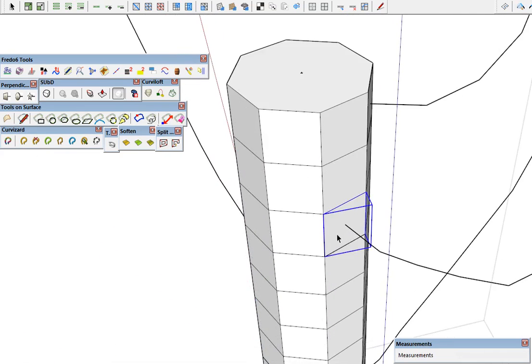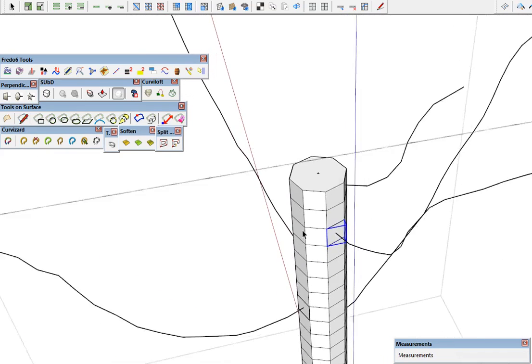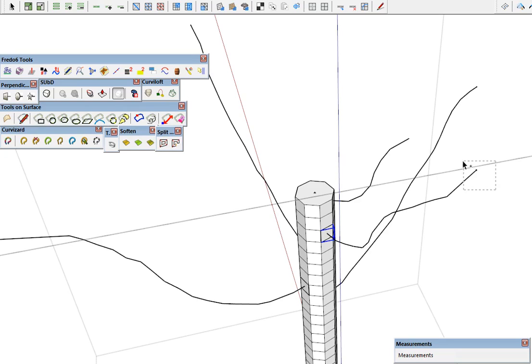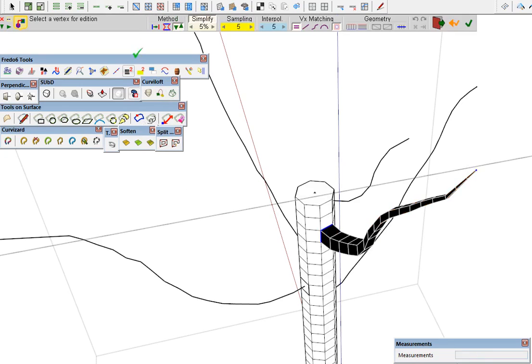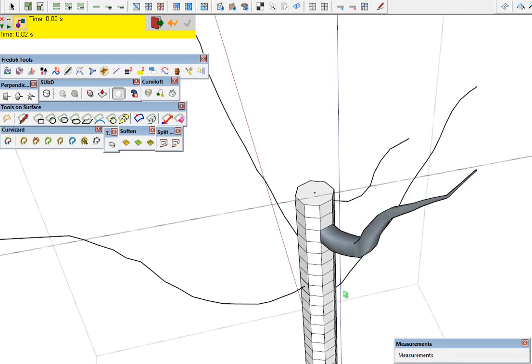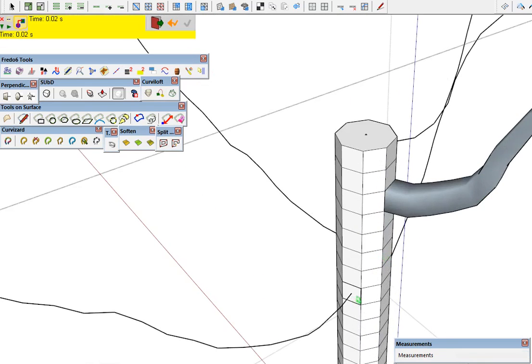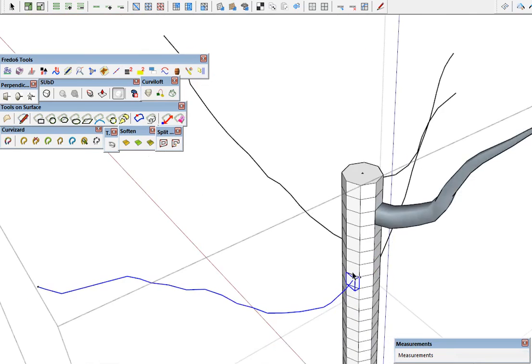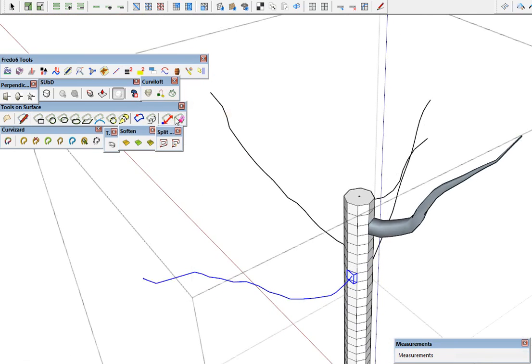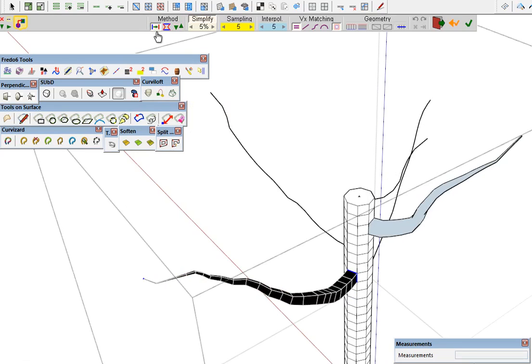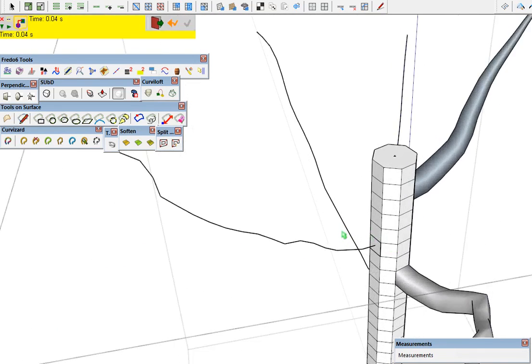So now all we're going to do is go in, select the square here. We can drag select right to left the square here and grab the set of edges as well. And now we'll run Curvy Loft. And we're going to just change the method to offset. Say OK. And we're going to go through and do all of these quickly. Change our method, accept it.